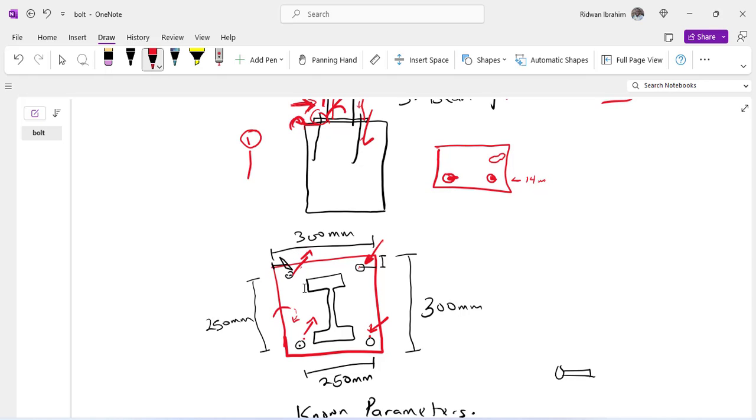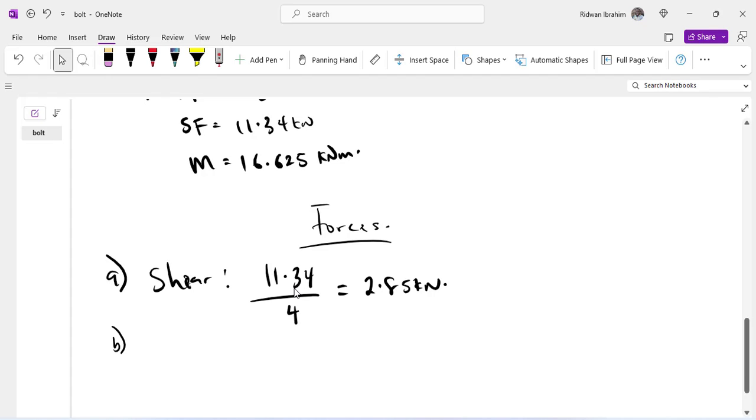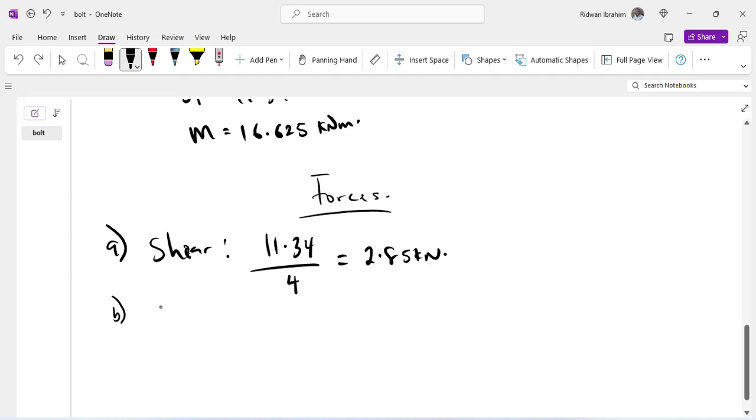So you can easily say that whenever you want to have pullout, it is 2 bolts that are working, and when we want to have shear, it is the 4 bolts that are working. Because for pullout, 2 bolts pull out while 2 bolts push in. When the bolt pushes in, it is not a failure, because definitely we push the bolt in before, but when it pushes out, that is a failure. As we have explained, it is the moment that will cause the pullout.